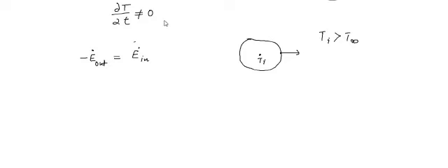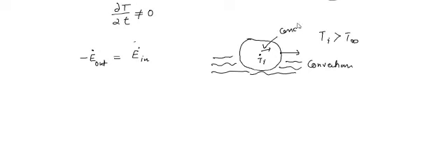Now as you know, in the figure the surroundings was liquid. Since it is a liquid or any fluid, the prominent mode of heat transfer from the solid is convection. So there is convection from here to here, and there is conduction here. But we know that in the lumped capacitance method we have considered that the temperature gradient is 0.